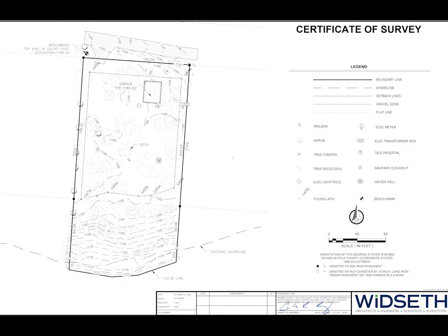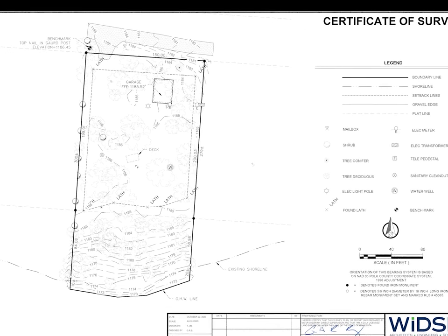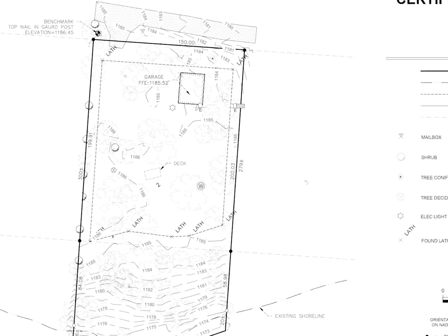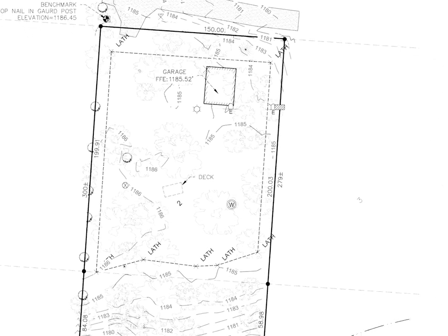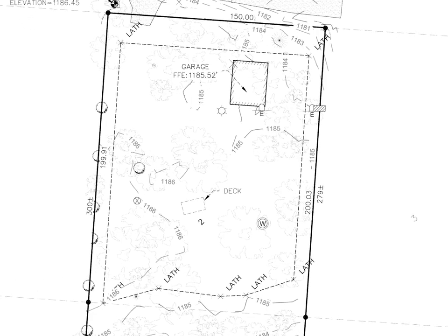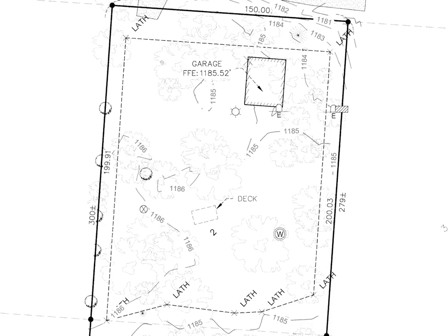We began our project once I had my 3 permits in hand, with inspections where indicated. The first inspection was the property line and lake high water mark setback inspection. I had to begin by having a lot survey to establish exactly where the property lines, historic high water line, and construction setback lines lay. The permissible setback is indicated by the dotted line on the survey.